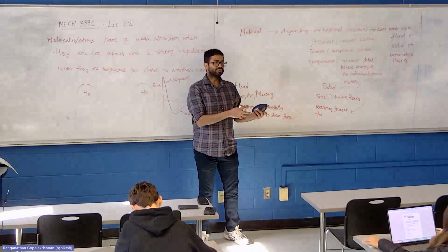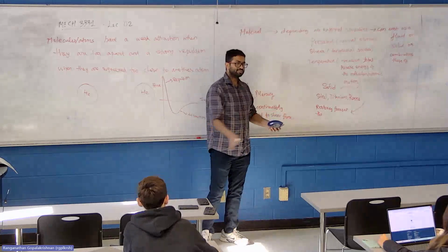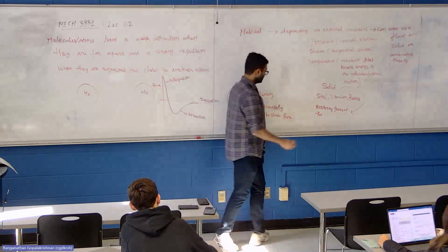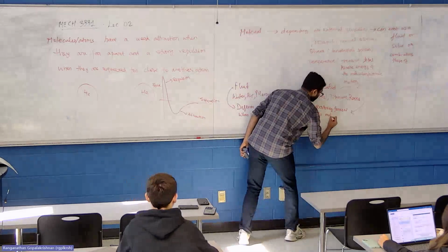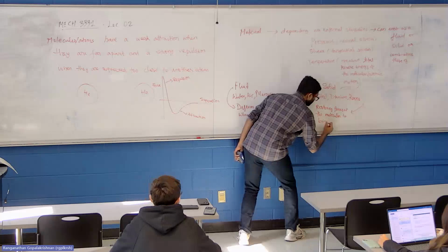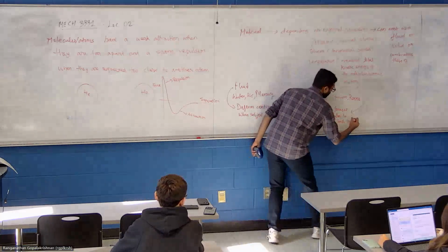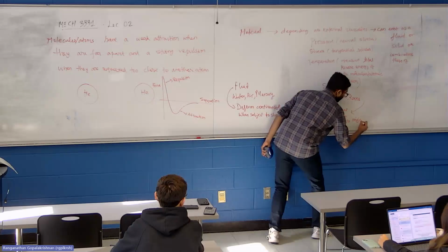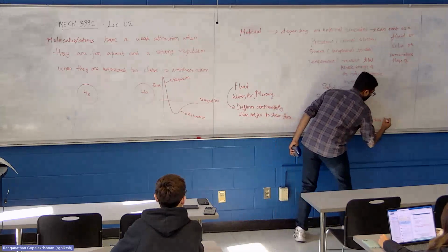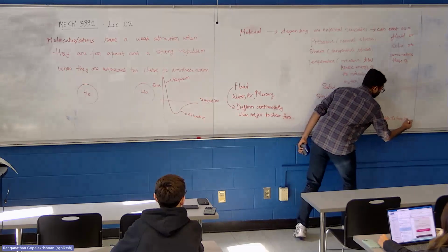In a fluid, those forces are much weaker. So once you shear a puddle of water, it just deforms continuously because the forces are so much weaker there, or almost non-existent, at the molecular level, to bring them back to original positions after the force is removed.